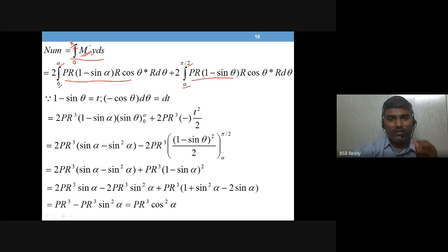Because there is a load applied between A and C. There is a point load. That's why the moment behavior is changing once you apply a load there. Otherwise, if there is no point load, from A to C you can have a single moment equation that will give you the moment profile. As you have a point load at point D, we need two moment equations to completely get the bending moment profile from A to C. So you have to break at D: A to D one moment equation, D to C another moment equation. That is what is split up here.